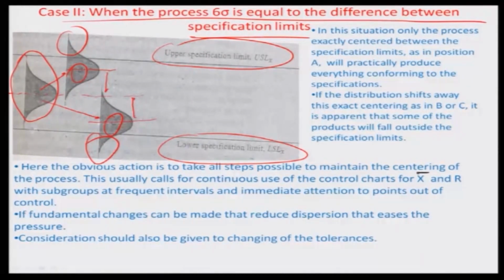So this is how you read, based on the upper and lower specification limits, the various control aspects of the chart. Another possibility in this case could be to revise the tolerance and see if it works out for this particular process, because obviously it is a very tight situation where the process mean and spread are just about good enough to be accommodated within the upper and lower limits, and a little bit of decontrol also leads to outruns and many rejects, as you can see here.